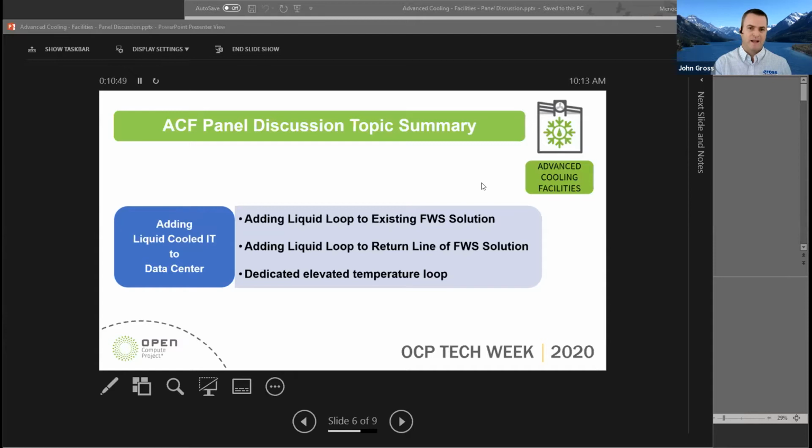But on the pumps connecting to and pumping to the CDUs provided by the ITE manufacturer, we had to look at the deadhead pressure of that pump. If we deadheaded that pump, what is the maximum pressure difference it could generate? On top of that, we had to look at the makeup pressure to that system, recognizing that that's going to be our minimum pressure to that system.